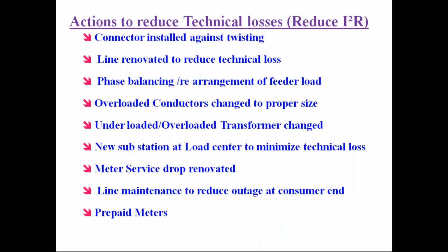In Bangladesh, for any new connection, we had a set rule of providing solar panels. Industry and commercial consumers have to have their own electricity through solar panels: for 50 kilowatt and above 50 kilowatt, it will be 10%. Only for garments, because garments is one of the main export products of Bangladesh, it's 5%. And for residential, for all load above 2 kilowatt, we had 3% solar panels to be established. This way customers were accustomed and rooftop solar gained popularity.